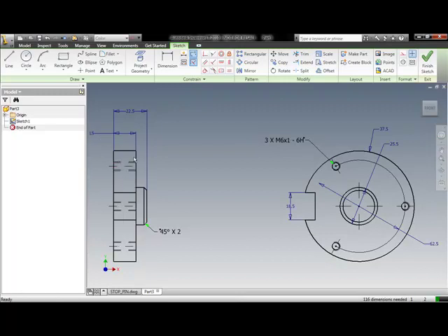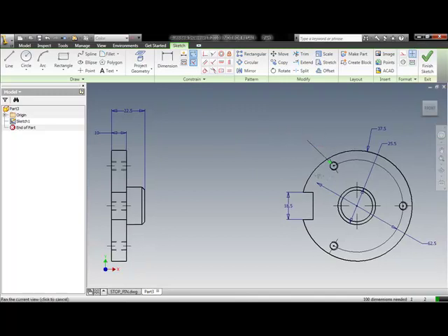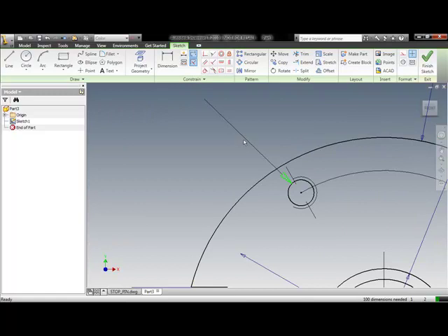So changing dimensions will update geometry. We also have some just annotations. These annotations are just user annotations or notes that were placed in the DWG file. I'm going to simply remove those because if they're not parametric inside of the modeling environment, at this point in time, I don't necessarily want them. If I can't trust them to be true and accurate and parametric, I prefer not to have them inside of my sketch environment. So let's go ahead and remove them.